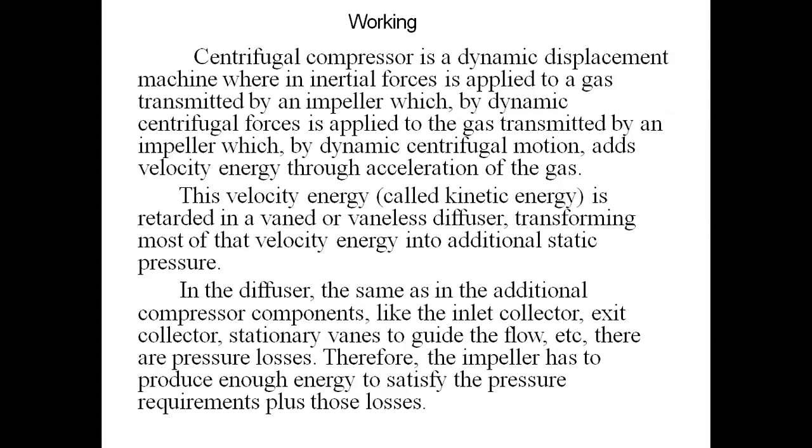The diffuser, like the other compressor components such as the inlet, exit casing, and stationary vanes to guide the flow, has pressure losses. Therefore the impeller has to produce enough energy to satisfy the pressure requirement plus those losses.